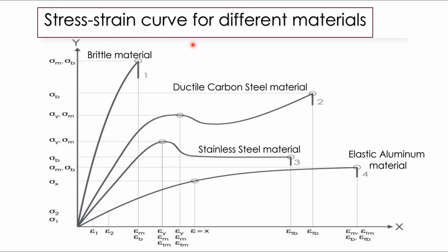Stress strain diagram or stress strain curve for different metals is different. Let's say we have 4 specimens, and specimen 1, which you can see here, shows an example of a brittle material breaking at yield with a very low strain value. Hence, the brittle material has minimum plastic deformation. It will fail suddenly and catastrophically once the ultimate tensile strength of the material is exceeded.